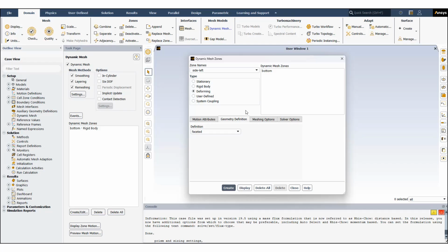For example, a piston that is moving up, then the mesh is just collapsing, compressing the mesh elements, and the elements that are in contact with the cylinder wall can move and slide along those walls. Faceted is the one that we don't need any setup. Everything's done by Fluent. If we choose plane, then we need to choose a point on the plane and the normal of the plane. Also moving in cylinder or use a UDF.